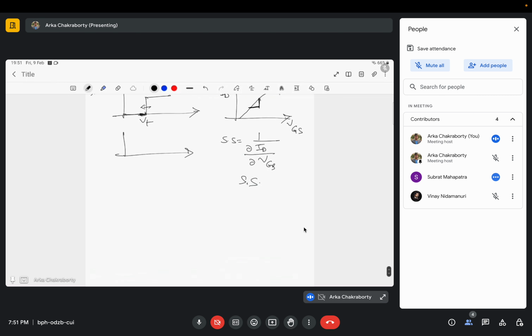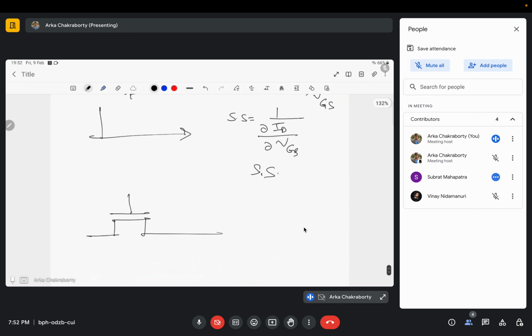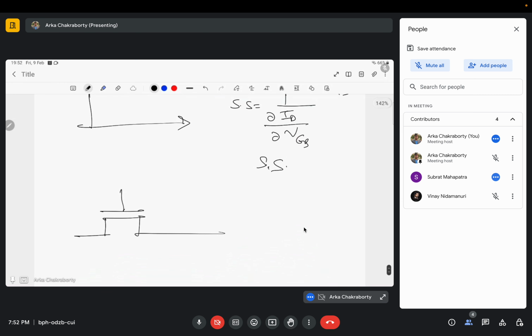And what you are talking about, GIDL or DIBL, drain induced barrier lowering, GIDL, gate induced drain leakage. Okay, see what happens. To make you understand, I have to go into much more depth of device physics for GIDL. See, simply speaking, there is an oxide here, T-ox, right? What is the thickness of this oxide? Very small, in nanometers. Not even nanometers, 1 to 2 nanometers, this T-ox is.